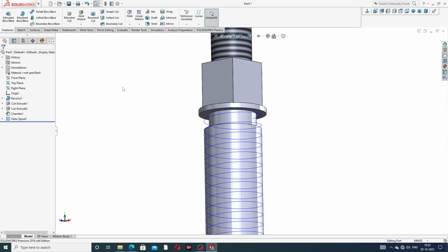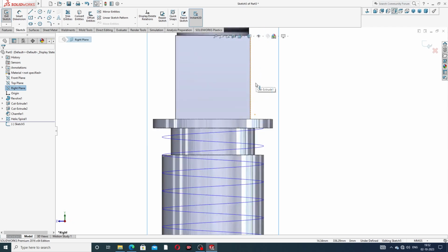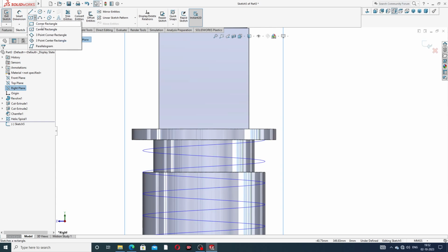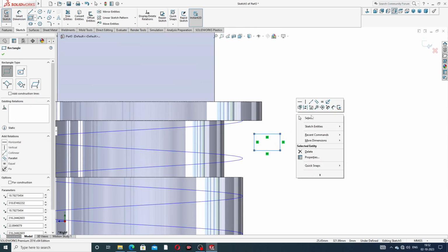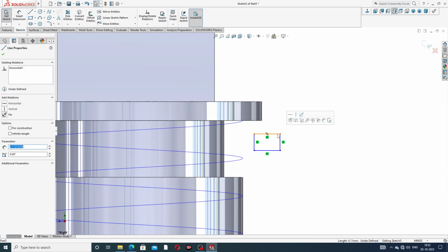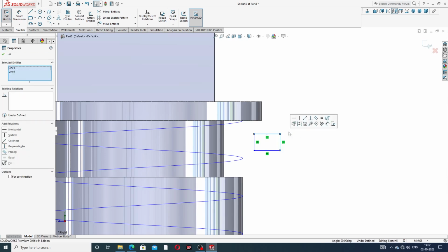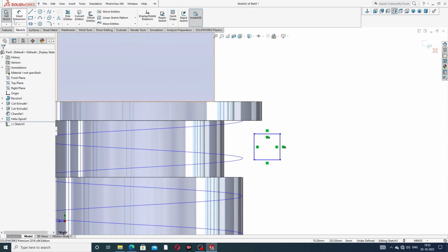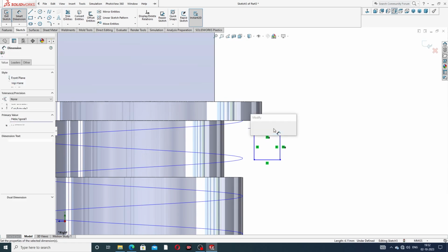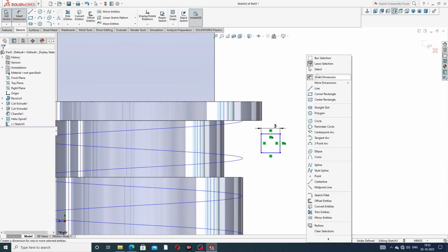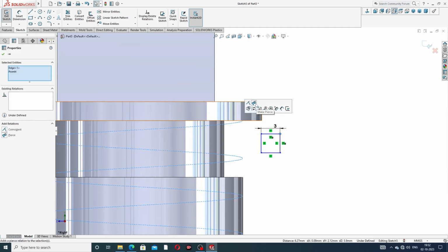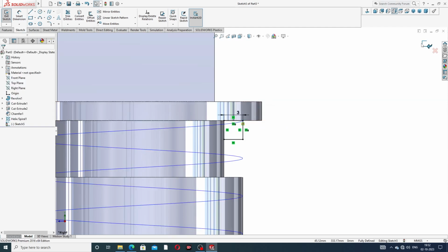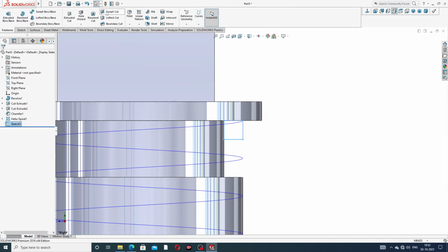and okay, and use a right plane sketch normal, okay, and draw a corner rectangle, and drawing a corner rectangle is this, and this is both lines select here and equal, and dimension is used here, a 3 millimeter is perfect, all is correct, and select this point and press the control button, and this line is selected here, and this use a pierce, okay, and exit, and use a sweep cut,